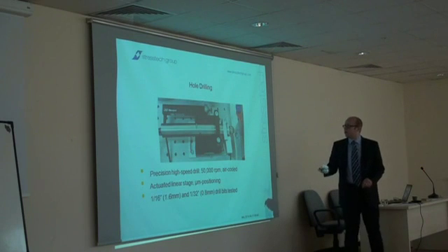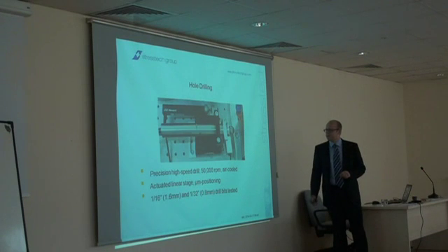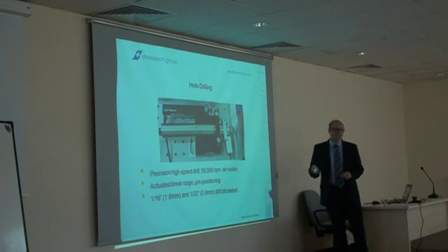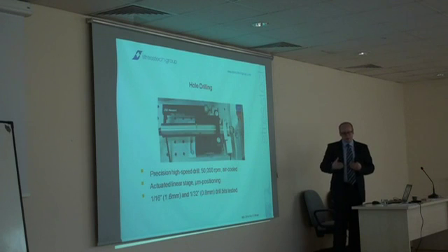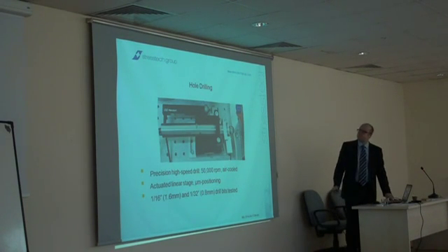Here's our drill. It's a high-speed drill. You can run up to 50,000 RPM. Here is a linear actuator, and it has to be micro-positioned, because quite often we would like to have a residual stress profile in 50 micron steps near the surface, so that we get enough information, for example, on shot peened samples or whatever. And here are typical end mills which we are using, 1.6 millimeter and 0.8 millimeter.